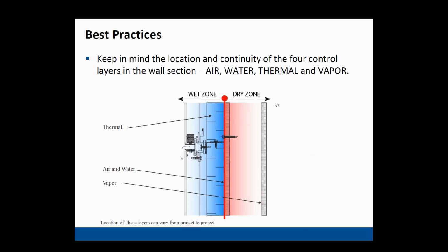Yeah, and when you're interviewing a potential fabricator, make sure that they have their testing for ASTM E330, which is the structural test. Yes, usually that'll separate the men from the boys, so to speak. Yep, and we include that as an informational submittal in our specifications also, that they have to show that they do in fact have that. But as Zeke just pointed out, it's better to know in advance than to be in construction and find out, oops, we don't have that.